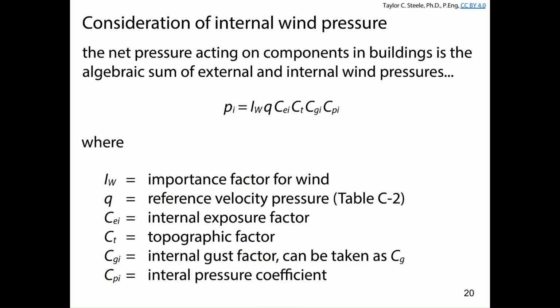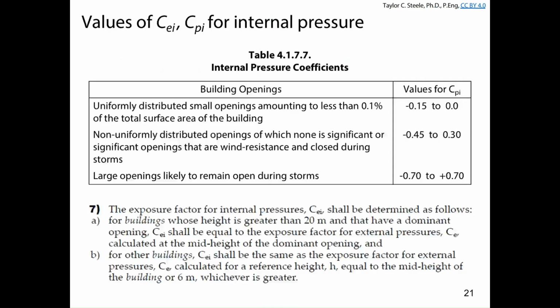Wind can blow in the window. What do you think is going to happen if wind blows into the window? What's going to be the effect on the structure? Inside pressure. Anyone blow up a balloon before? Expands, right? So the building's going to want to poof up. And so from time to time, you're going to need to consider that, especially on roof framing or on cladding components. Where it's really important is stuff like garages that are going to remain open during large storms.